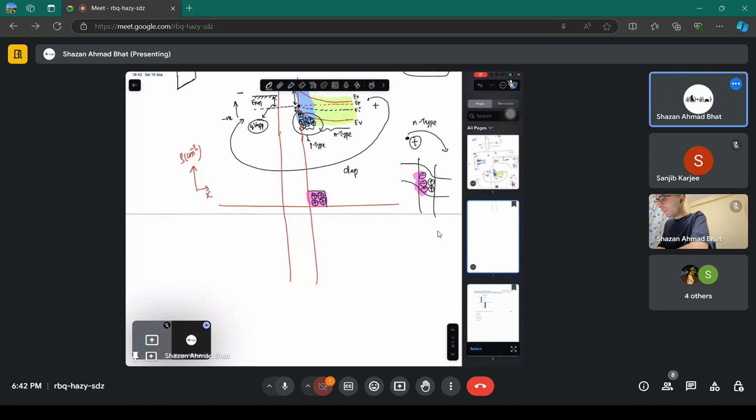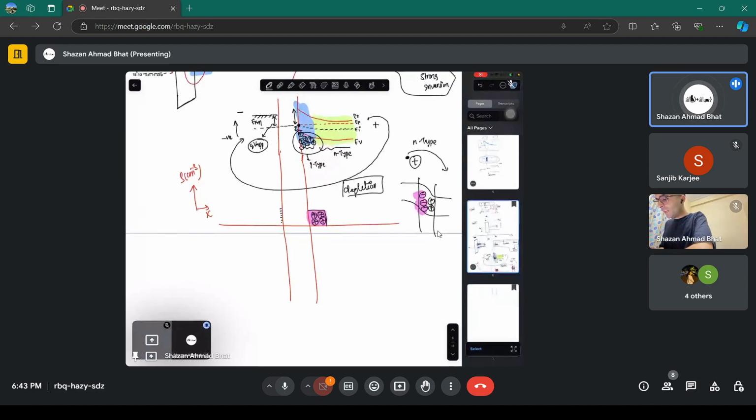This is in depletion. That's why this regime is called depletion, because you have depleted the region near the oxide and semiconductor. On this particular side, you get negative charges, which are the free electrons, and you showed them as a delta function because they are mostly localized first near the metal oxide interface. There are so many electrons present in the metal that they instantaneously form a kind of delta function near the oxide whenever you apply a field. They are the ones to respond.